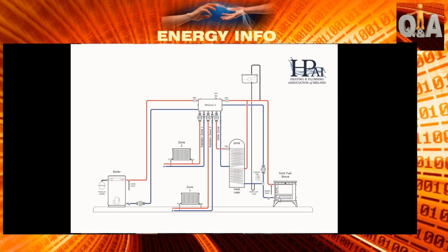What's the danger with 80 degrees? Why 80 degrees? 80 degrees is when the water coming back to the stove reaches 80. Between 80 and 100 there's very little difference in the density of the water, and the thermosiphon starts to slow down completely. Okay.